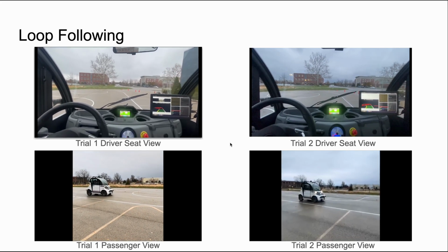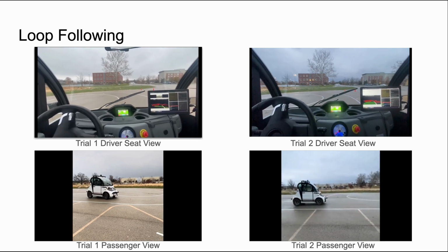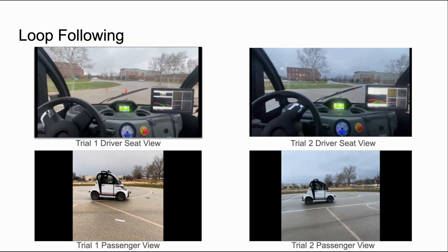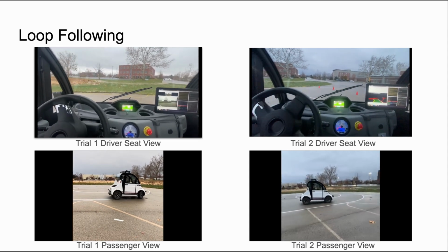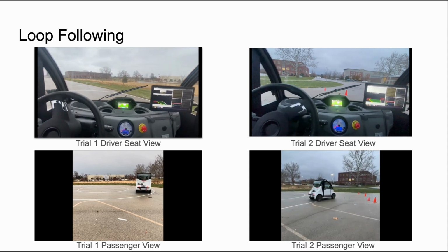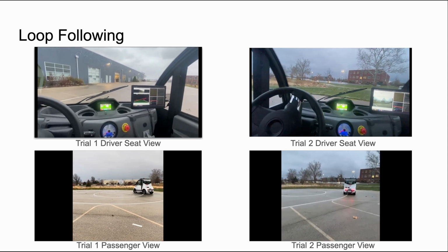Now, let's see the final results of our lane following controller on two trials. Our deliberate use of 1 meter per second for the PID controller's desired speed is to synchronize the YOLOv2's outputting rate with the car's movement. The car will safely finish the loop without rollover nor driving off the track due to our controller logic.